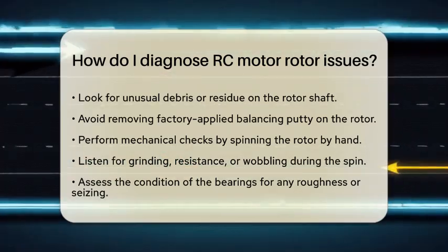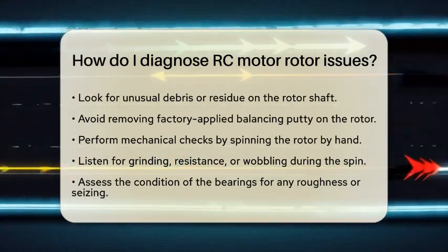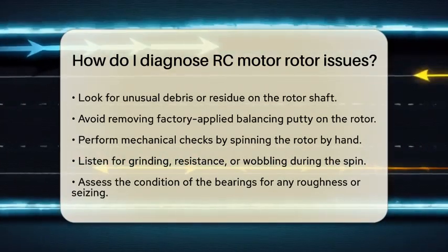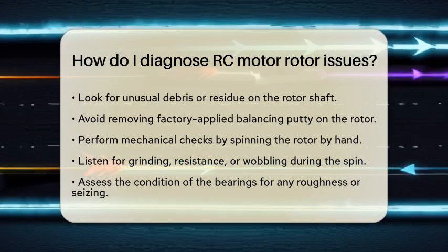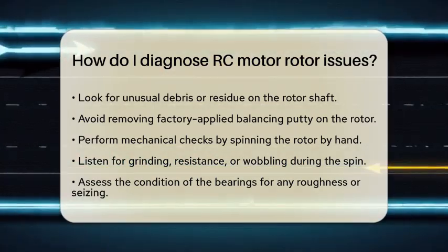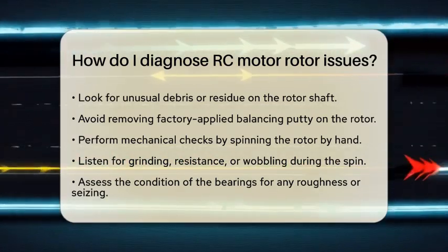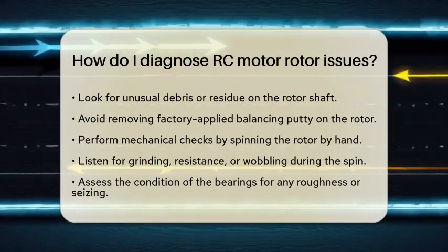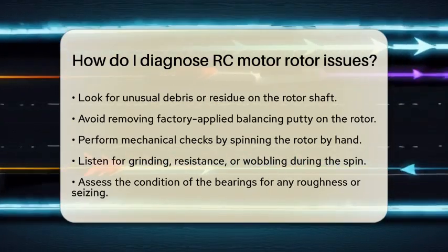Now let's move on to mechanical checks. Spin the rotor by hand to feel for smoothness. If you notice any grinding, resistance, or wobbling, this suggests mechanical issues. Check the condition of the bearings as well. Seized or rough bearings can affect rotor performance and may mimic rotor faults.